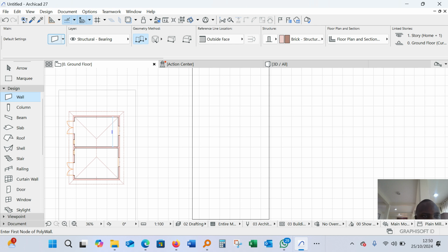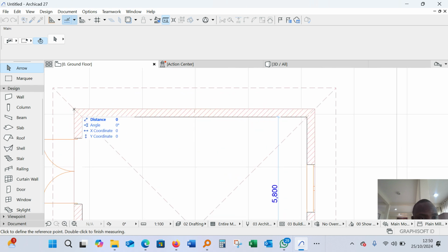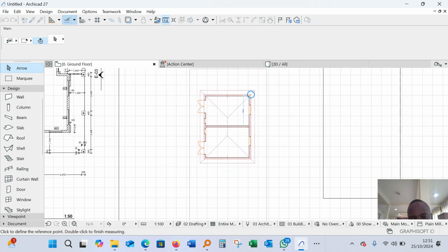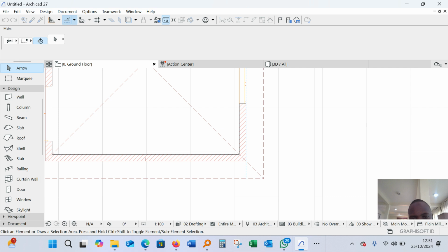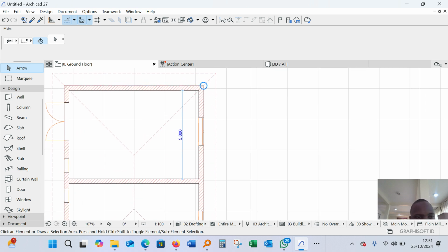So right now we are selecting our wall, and the length that we had, we choose a 9.1 wide house by 9.1 by 12.6. Whenever you tap on M on your keyboard, that's how you can measure. When you tap on M, you can easily measure off that distance.